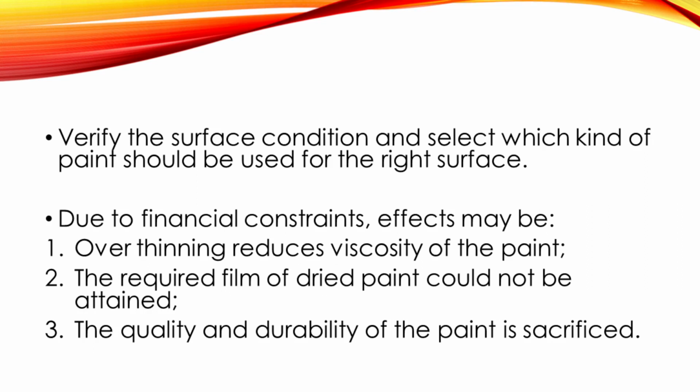So there are instances wherein, due to financial constraints, the owner requires his painter to expand the coverage of the paint contrary to the label specifications, and the effects are: 1. Over-thinning reduces the viscosity of the paint. 2. The required film of dried paint could not be attained. And lastly, the quality and durability of paint is sacrificed.